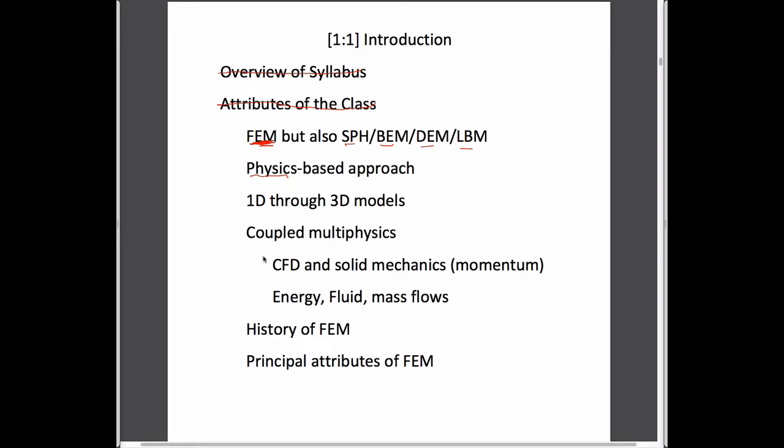But the real crux of this activity is to talk about the coupling between models. We've made the case already that effective stresses driven by chemical changes, thermal changes, fluid pressure changes, and maybe loading changes in the total stresses applied, have some influence on permeabilities and therefore on the response of reservoirs. So that's really the emphasis of this class: how do we couple those fields together to figure out what the evolution of effective stresses is.